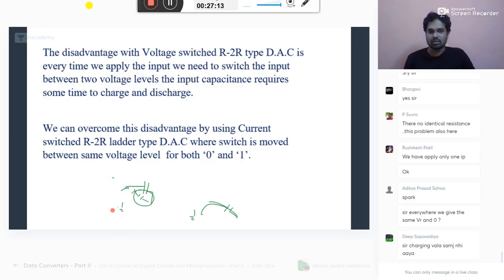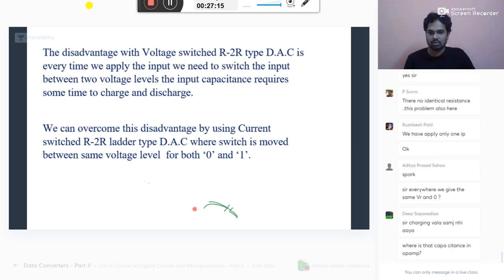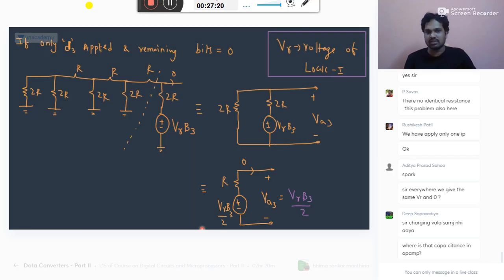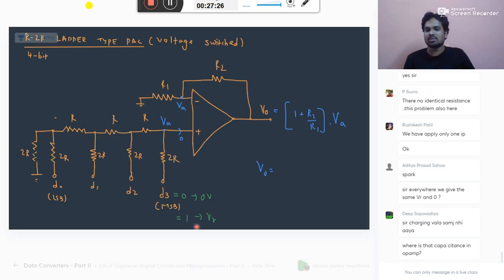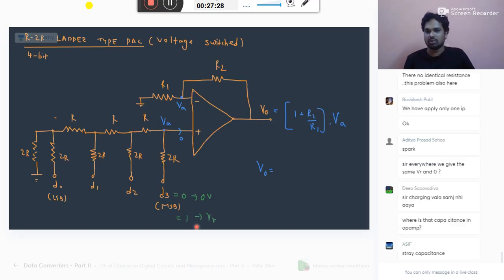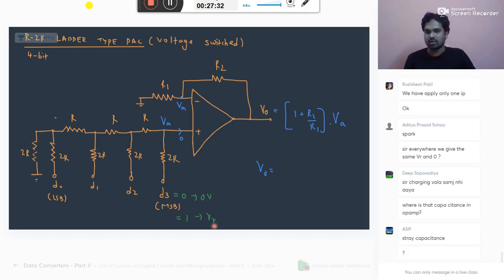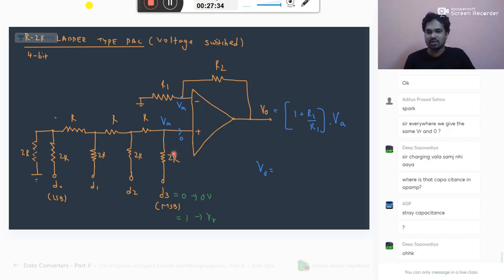See here. Your total circuit is made of transistors, MOSFETs only. Any switch is made of MOSFET. Your MOSFET has internal capacitance at the input, or you can take the op-amp input capacitance. The capacitor may not be physically present.